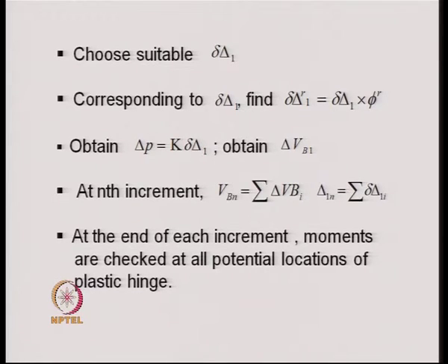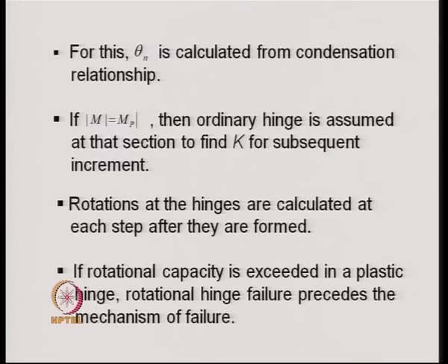At the end of each increment, moments are checked at all potential locations of the plastic hinge. That part is a little complicated, in the sense that first one has to find the value of theta n at the cross sections from the condensation relationship.